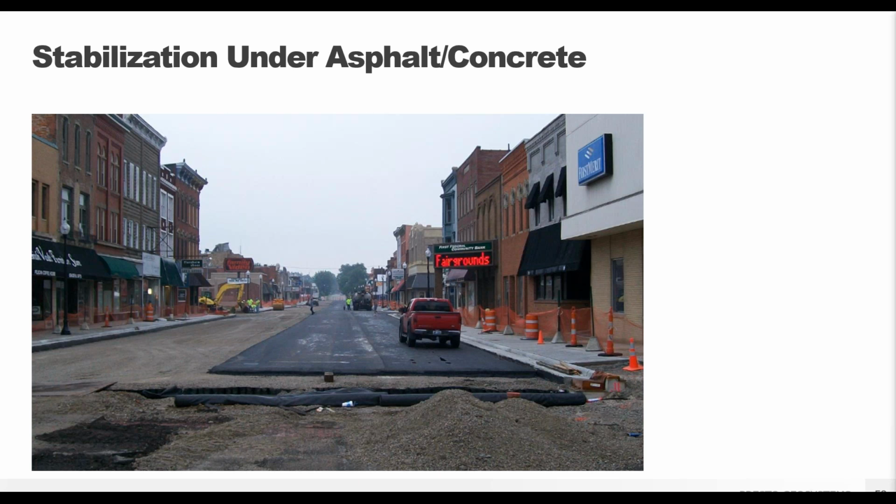And so you can actually place your asphalt layer directly on top of the GeoWeb panels, and you can place it again before you finish paving the entire road. So again, you can have that nice staggered construction, and you don't need to have cure times. You don't need any special equipment. Your standard asphalt paving equipment is going to do the trick.